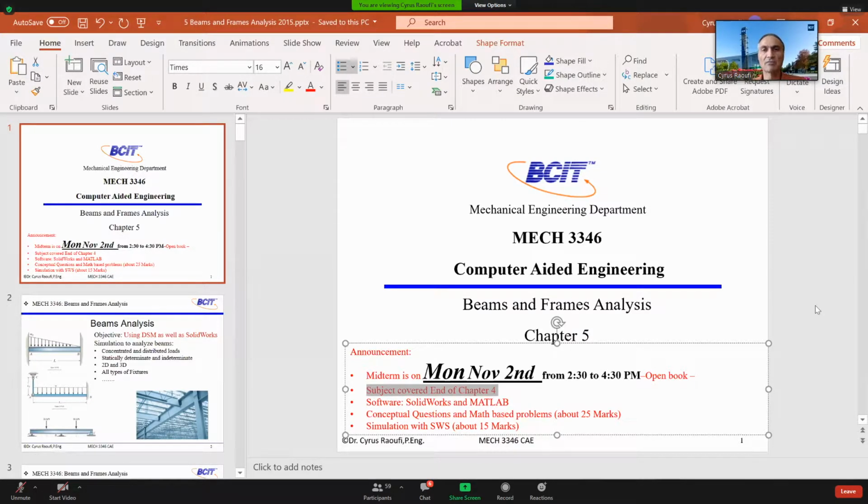Then you have the global stiffness matrix, the force vector, and the displacement vector. Put them in that equation and solve the problem. The problem will be based on the number of unknowns and the number of equations, and when you apply the boundary conditions in terms of load and fixturing, you end up with a simplified equation. You are not going to solve it by hand, you are going to use MATLAB. That was the one directional beam element.